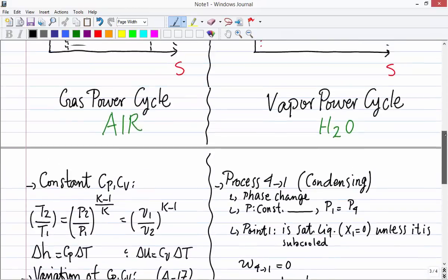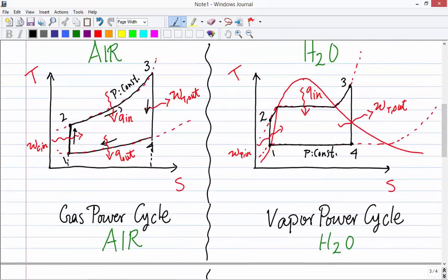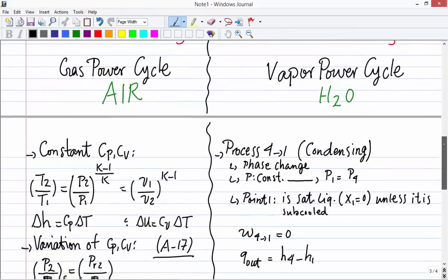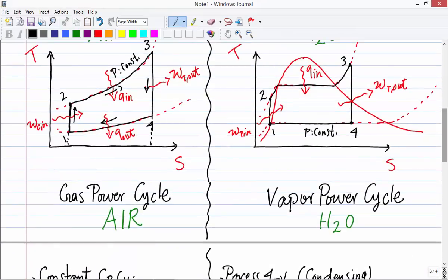I assume that you remember when we subcool a liquid, all the properties would be chosen at a specific temperature. Pressure does not matter anymore because the liquid is incompressible, and when you change the pressure, it's just the potential energy, just pressure is changing, right? But when you read for the properties, you should go at specific temperatures. I'm gonna show this when I'm solving the example.